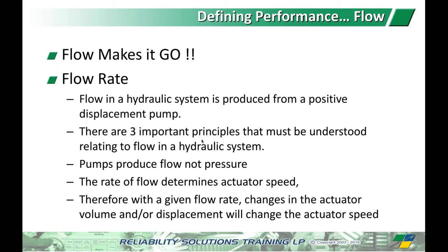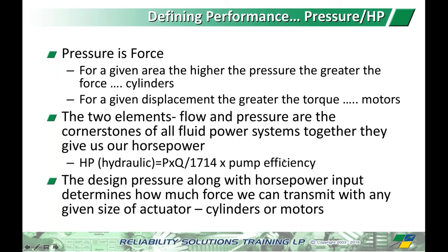So if I've got an actuator that's not actuating fast enough, the last thing we should probably do is start playing around with the pressure regulators. But what's the very first thing we typically do, right? Whenever we have a problem with the hydraulic system, let's start cranking on relief valves and pressure regulators. It's not about pressure, it's about flow. Find out where the flow is going, or find out why you don't have the correct amount of flow. So rule number one, flow makes it go.